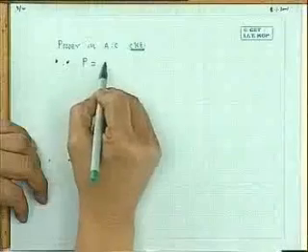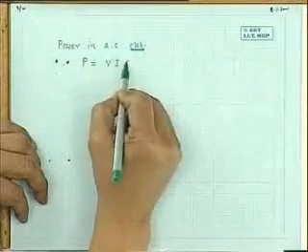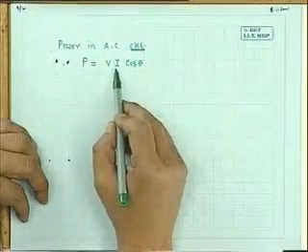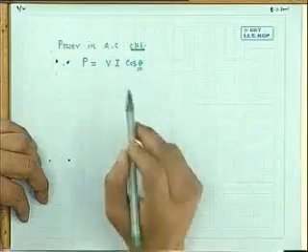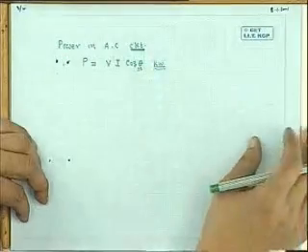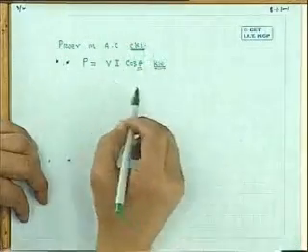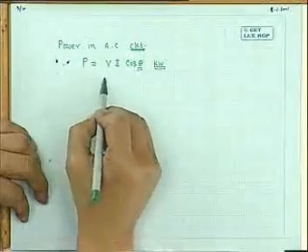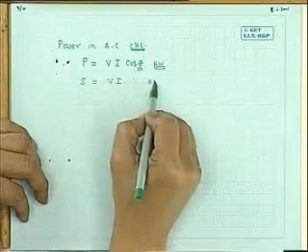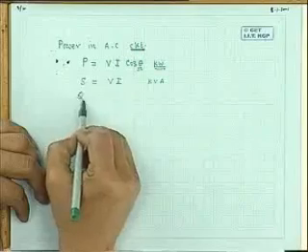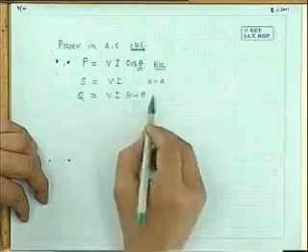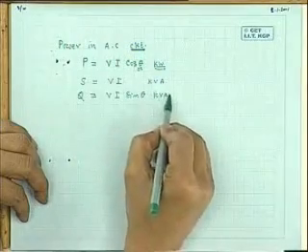and steady state has reached, and the expression of the power you know will be V into I into cosine theta, where V is the RMS value of the voltage, I is the RMS current, and theta is the power factor angle. And we give a name, kilowatt. The primary thing I want to tell here, apart from this, there are quantities called VI, whose rating is kVA, and another quantity called Q, which is called reactive power, which is VI sin theta.